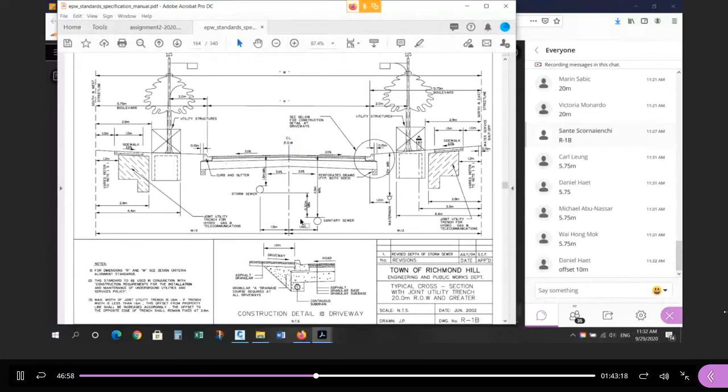Okay, so this is, I don't want to say it's a mystery, it's not a problem. It's something you need to look into, right? What kind of road am I designing for? I know it's a ULU 20. I know that the width is 20. I know that the pavement dimension is 8.5. Based on this section, I know that the center line of the right-of-way is the center line of the pavement. I can now draw my center line throughout on this typical 20-meter right-of-way. There are exceptions, and you'll see when we go to draw this. What happens through the bulb, the cul-de-sac, what happens in the elbow, and how we deal with it at the intersection, you have to look at it in a little more detail.